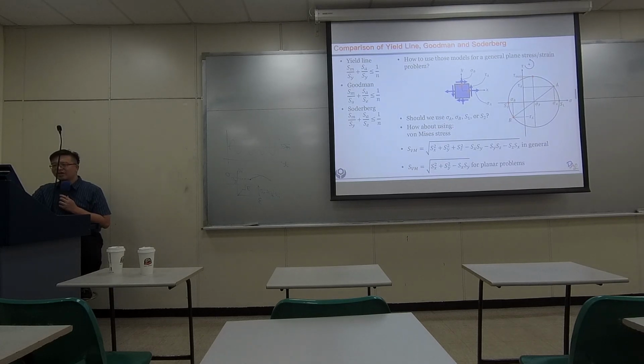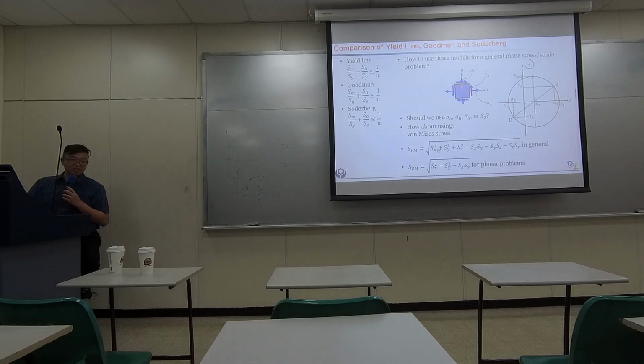So there is a good way to introduce the effect of shearing stress in those fatigue models. That way is to use the von Mises stress, because von Mises stress is like an equivalent stress without direction. It has the unit, it has value, it has dimension, but it has no direction. It's an equivalent stress that represents the stresses in all directions. Okay?